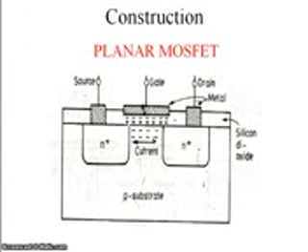A simplified structure of an N-channel planar MOSFET of low power rating is shown. So on a P substrate, two heavily doped N+ regions are diffused. Now an insulating layer of silicon dioxide is grown on the surface.